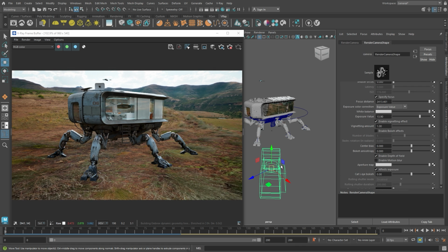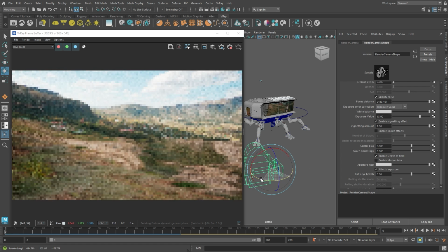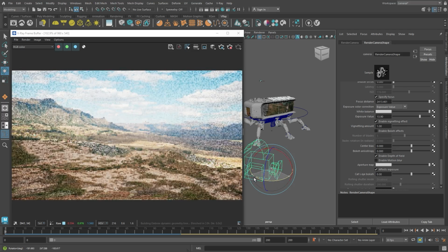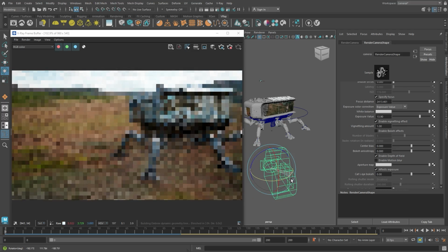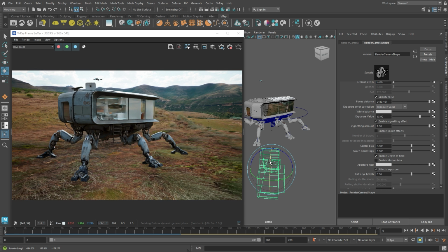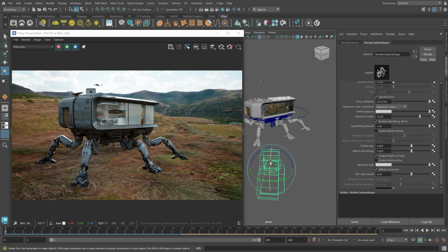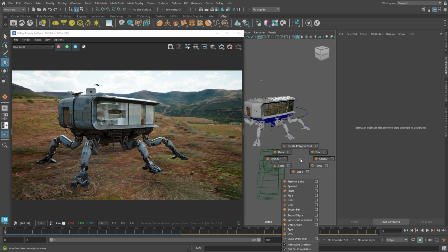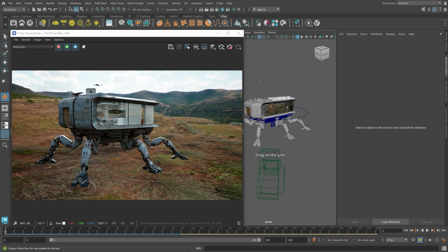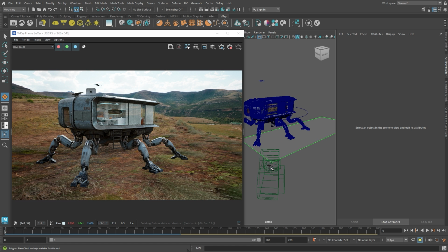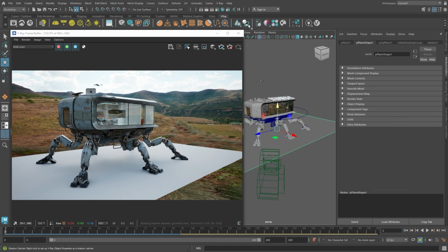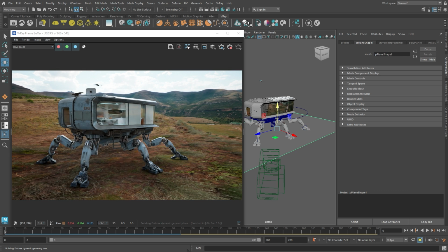So now the house looks like it's staying on the ground. But does it really? The answer is no, because we're missing the shadows. We don't get any shadows because there is no physical objects to cast shadows onto. The ground of our dome light is just a projection. To get some shadows on our ground, we'll use the V-Ray Shadow Catcher. All we need to do is create a plane and click on this icon. That's it. Now our house looks like it's part of the environment.